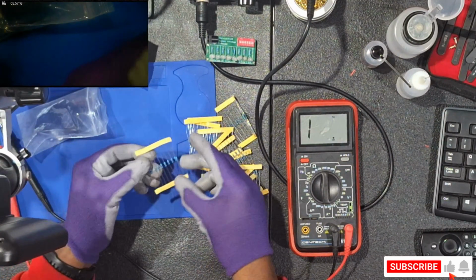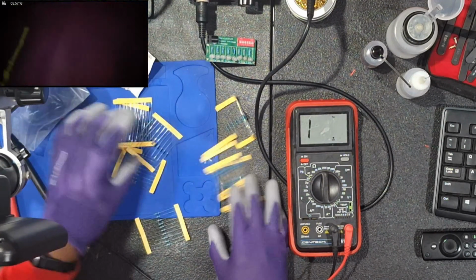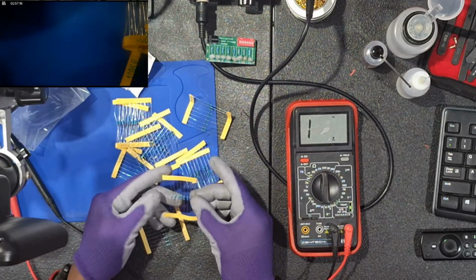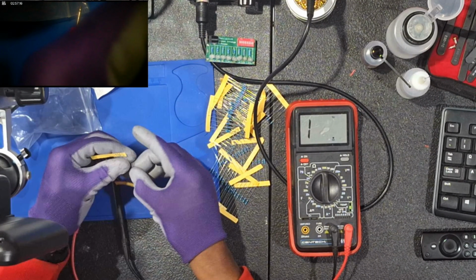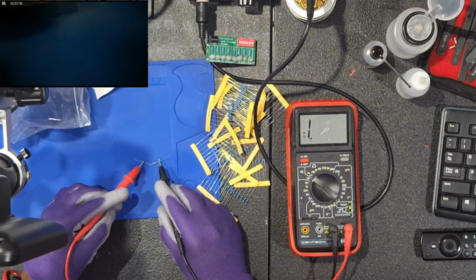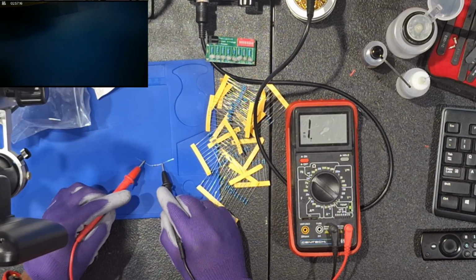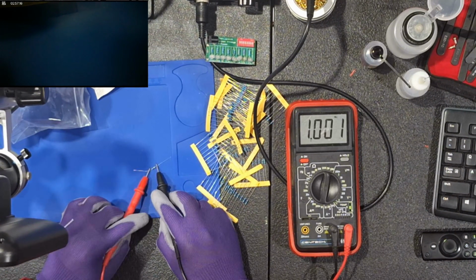But what if I have a resistor and I don't have any labels for it? It's not on a circuit board that's labeled, and it's not in a pack that's labeled. How would I find it? Same thing applies. I would just start from diode mode and work my way up with each dial. So go to diode mode, then to 200k, then to 2k, 20k, and so forth, all the way up to mega ohms if you have to. And that's how I would find all the values for the resistor that I'm working with.